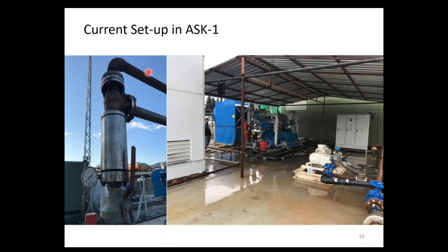This is the line where the motivated fluid comes. This is the line where the NCG comes. There is a special ejector motivated fluid system in here, and it should be specifically designed to not make any restriction. After passing through the ejector section, it should go down continuously without any restriction, and after that you can close it anytime you want, just to bypass.